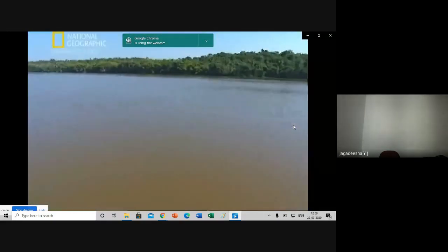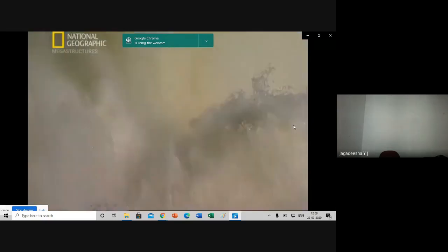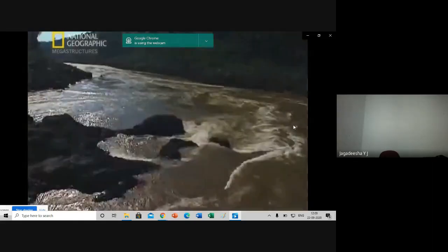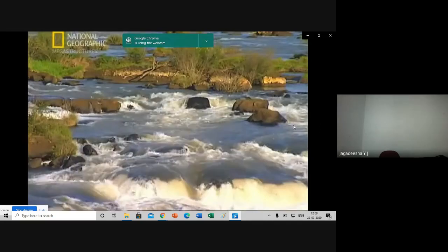Brazil was thinking big. The government wanted one massive dam to supply a huge chunk of the nation's energy demands. Finding the perfect site for such a big dam wasn't easy. The river had to hold a volume of water great enough to produce the energy needed. It must flow through narrow banks, and its bedrock had to be strong enough to take the massive weight of the dam walls.